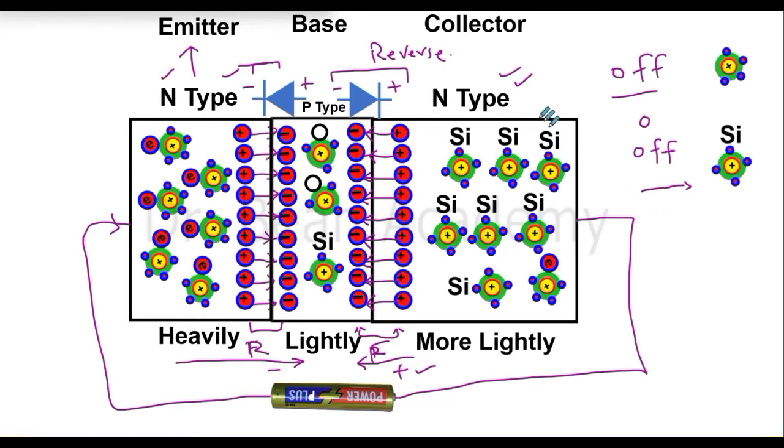But always remember that this n-type, which is the collector, and this n-type, which is the emitter, are different. Now these junctions are different, you see. Their areas are different, and these different areas will matter later when I explain their operation in more detail. And then the doping level is different. So these two terminals are different. They are not only n-type.